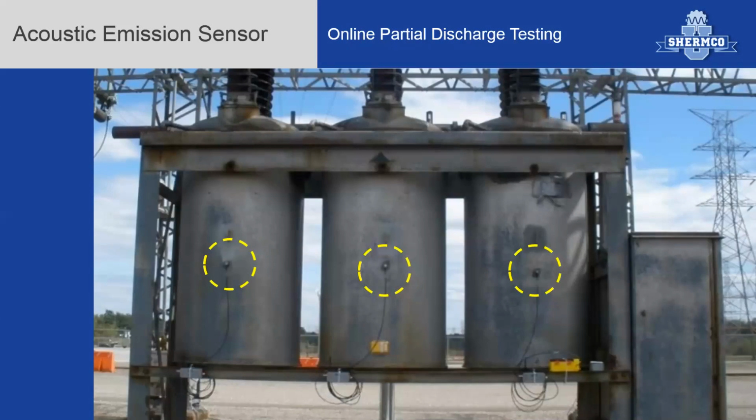The image here basically shows an oil breaker in a yard, and we see that there is a contact sensor placed on each of the sections of the breaker. This particular one goes down into a little module, and these are more permanently installed and are continually sensing. Again, these sensors can be temporarily installed for long periods of time, they can be permanently installed for continuous monitoring, or they can be detachable, carried with a PD receiver, and just probed along for scheduled surveys.